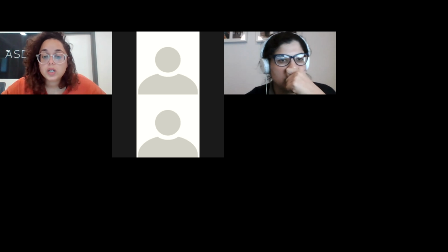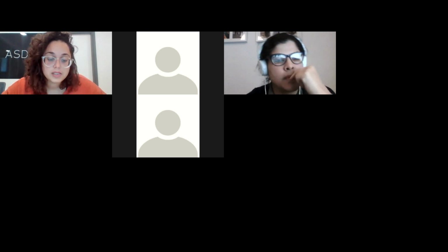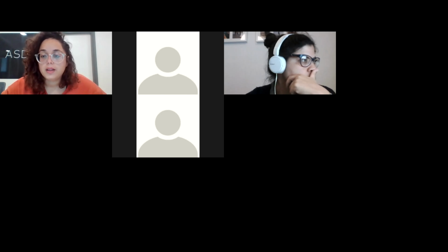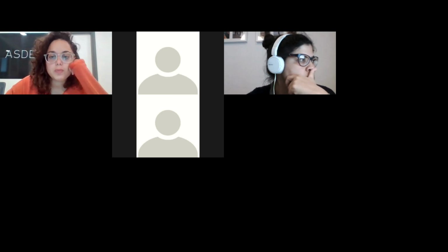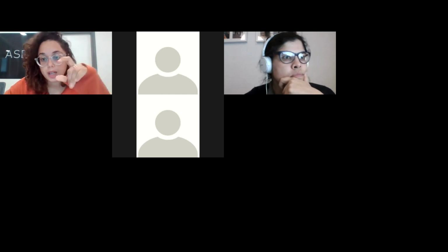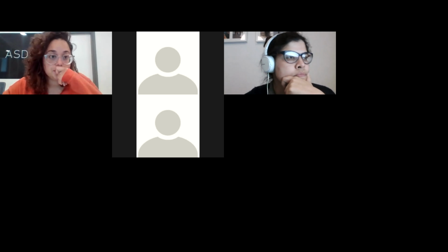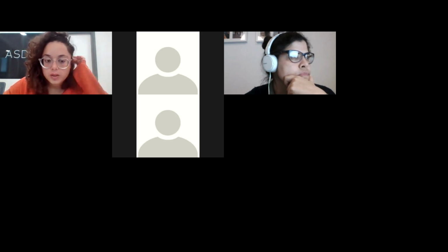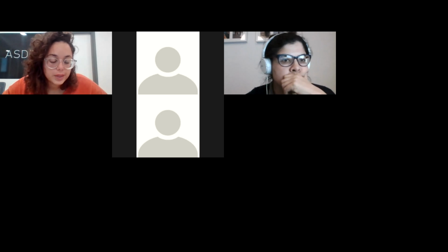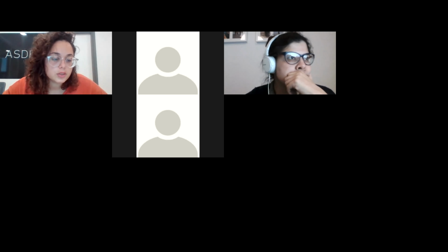And you can do it with macro elements, with micro modeling, just by using shell elements, or if you want specific elements, both for brick and mortar. And of course, this is the easiest way to do it with the shell element, because it's less time consuming to model. Let me find you the video that I was talking about.